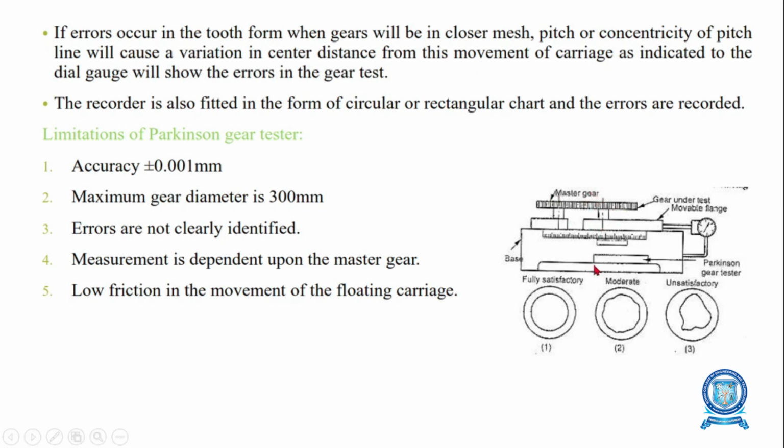The right mandrel can be moved along the table and clamped at any desired position. The left mandrel slides against the pressure, and it has a limited movement. The two spindles can be adjusted so that the axial distance is equal.